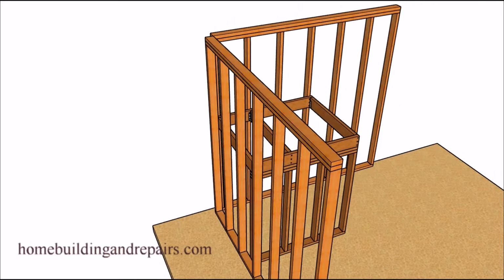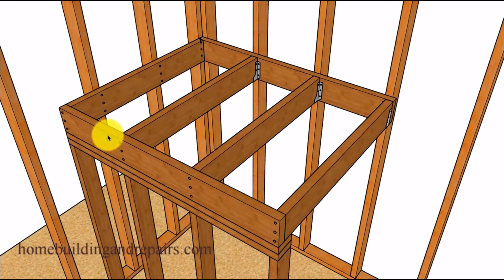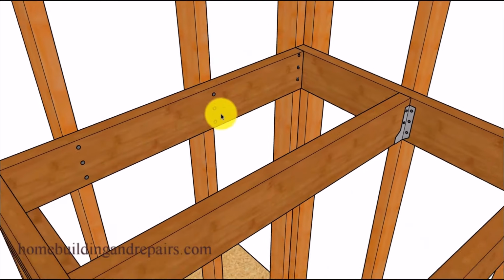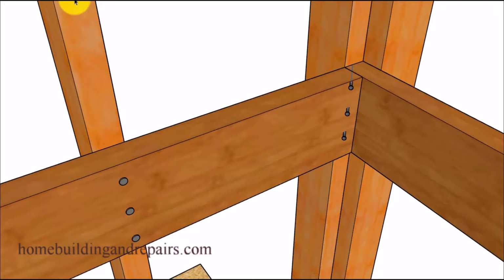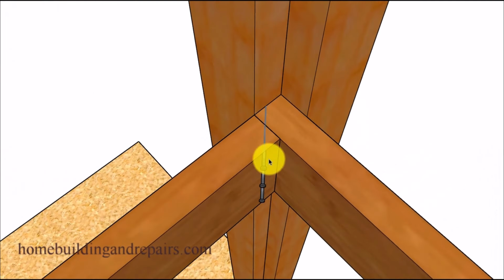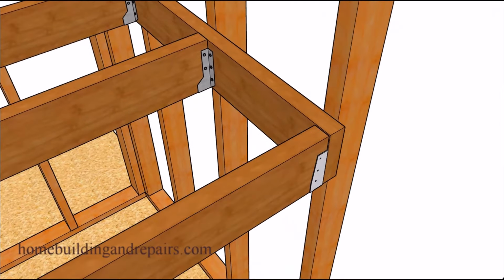And in our next example, we are going to have two walls that form a corner, and in this situation the landing will be built basically the same, except you're going to be able to nail this joist to the wall framing, and you will even be able to attach the end of the joist here by using an angled nailing pattern like this one, where the angled nail can go through the joist and then through the other joist and then into the wall framing stud. And of course, if you are using a nailing gun, that's going to be quite easy to do.